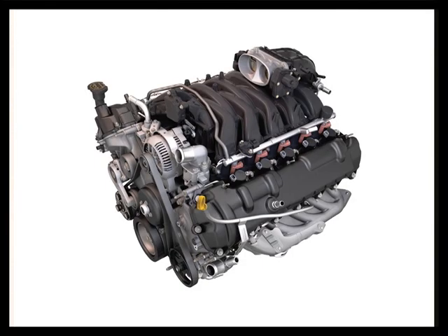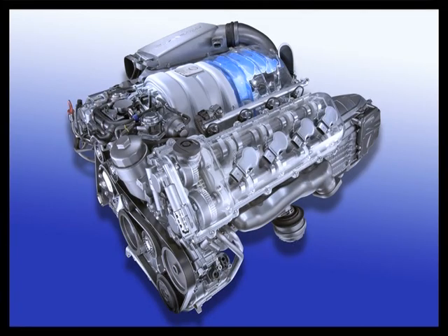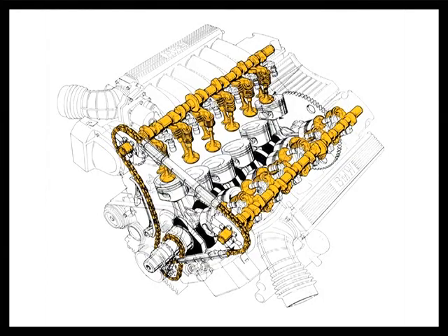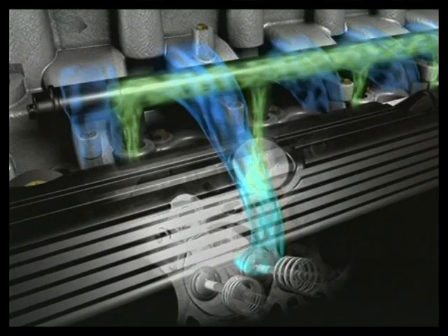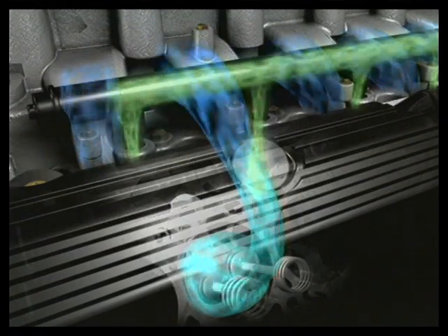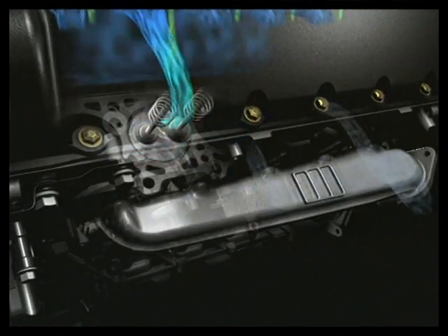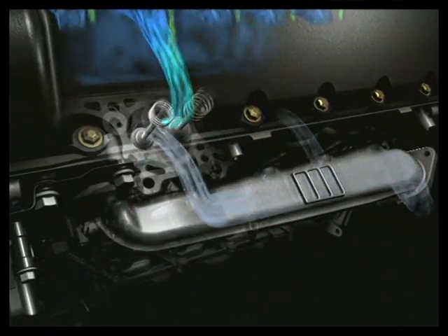Additional cylinders smooth engine operation because there is less time, degrees of crankshaft rotation, between power strokes, and they generally also increase power output. You should now have a basic understanding of how an internal combustion piston engine operates.